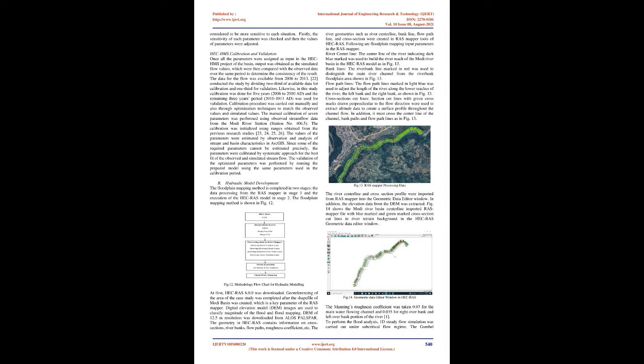The computed characteristics for river included river length and river slope. Similarly, computed characteristics for basin included basin slope, longest flow path to the basin, basin centroid, centroid elevation, and centroid longest flow path. To calculate basin slope, the watershed slope was required, which was calculated using the ArcHydro tool.